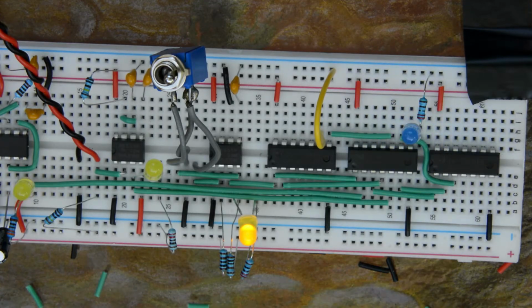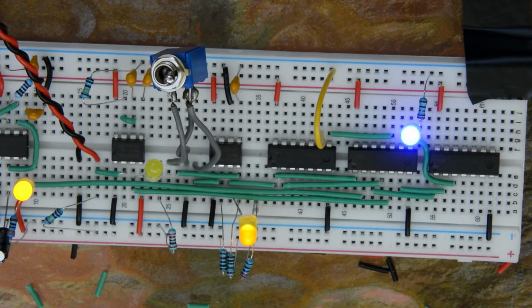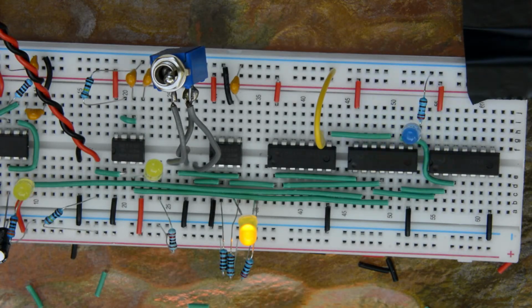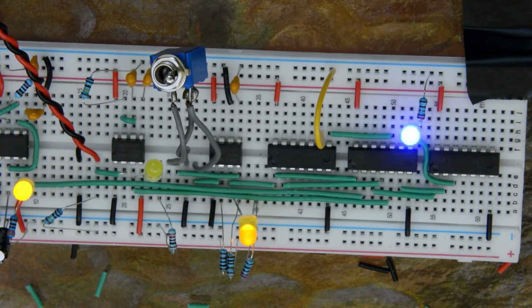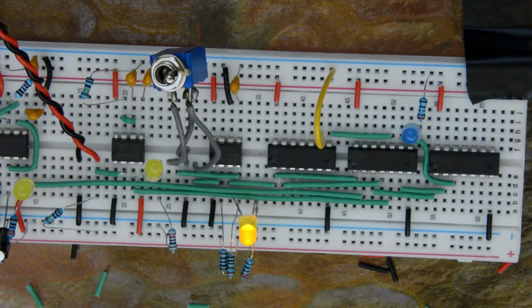This third 555 really sort of passes through all of the actual comparator logic. It just uses pin 4 and I forget pin 2 to directly control the SR latch that's built into the 555. Then we have just a bunch of combinational logic to actually mux these together, basically.